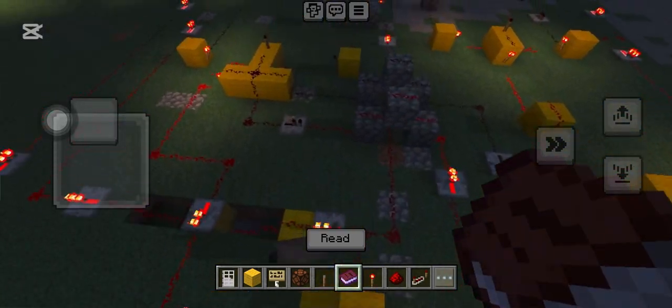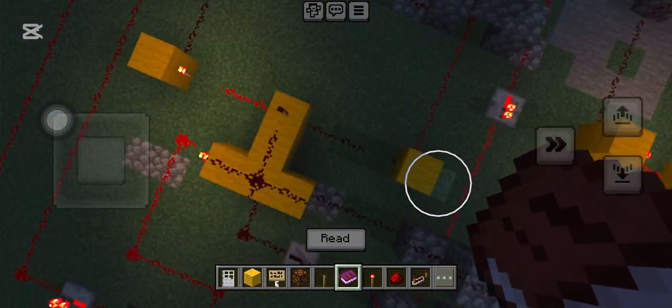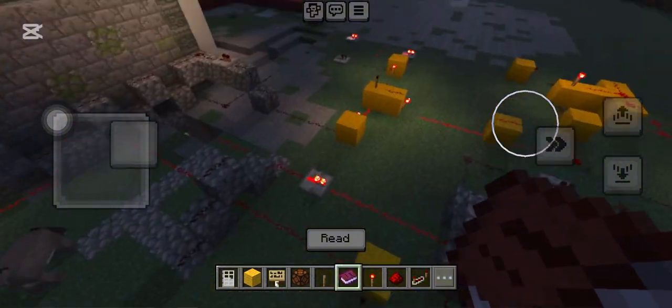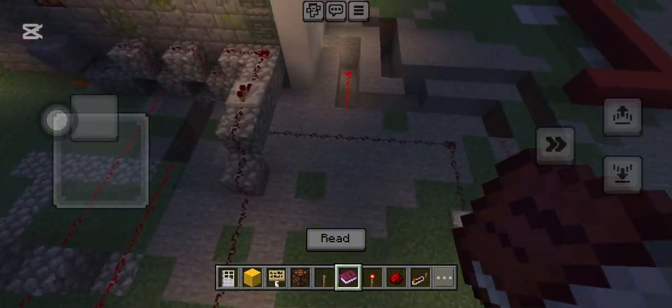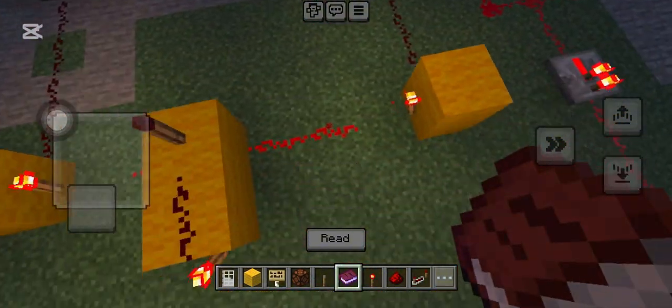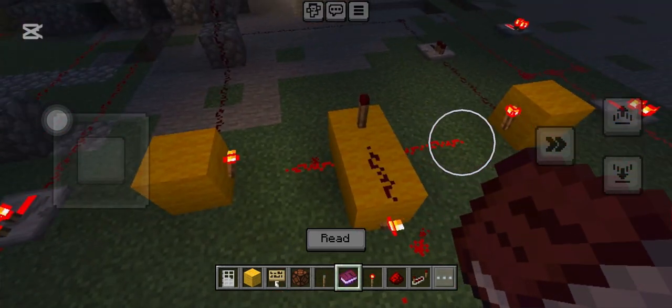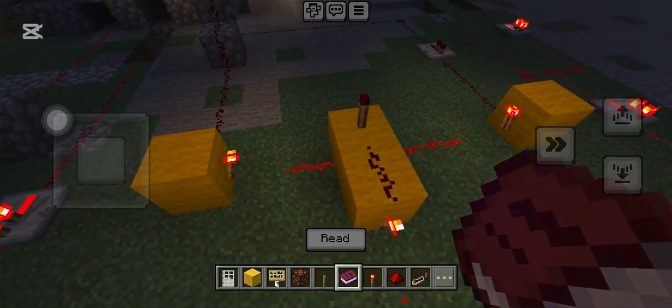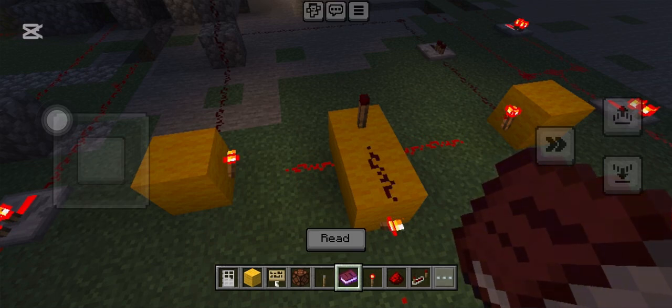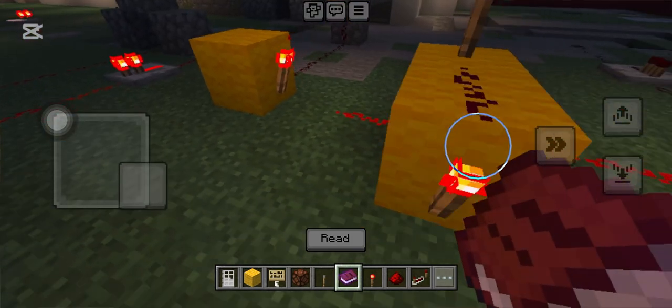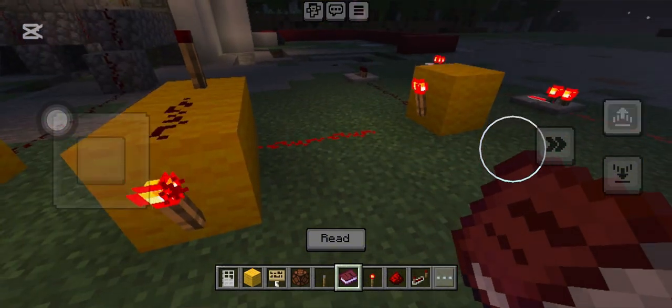Next we go to A2 plus B2. It works kind of similar to A1 plus B1, you just need to add more sum logic. So we have the AND gate the same. The AND gate just checks if both A2 and B2 are on at the same time. The output is called the partial carry. It's not a final carry yet, since we still need to combine it with the bit 1 carry later.